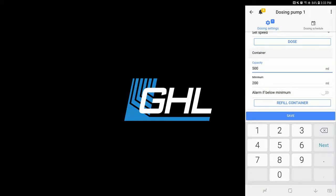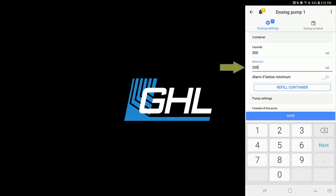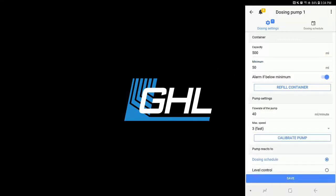Next, enter a number into the minimum field. The number you enter here is the threshold for when an alarm should be triggered. If you'd like to trigger an alarm when the fluid level of this container drops below the amount entered here, activate the feature by tapping the switch icon. Otherwise, leave it disabled and no alarm will be triggered. The next step will be to specify how many milliliters are currently in your dosing container. Select Refill Container and enter the approximate amount.